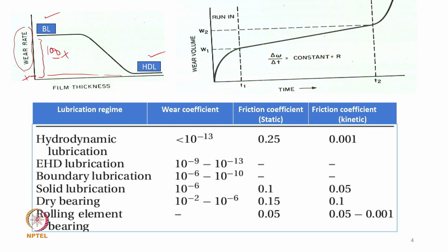However, this is for the comparison only between BL and SDL, but more or less the same thing will happen with ESDL also. The elastohydrodynamic lubrication mechanism, or we can say directly the EHL case, more or less a similar kind of curve will come in this case also. But you see this figure, which says very clearly that with time surface degradation will occur.